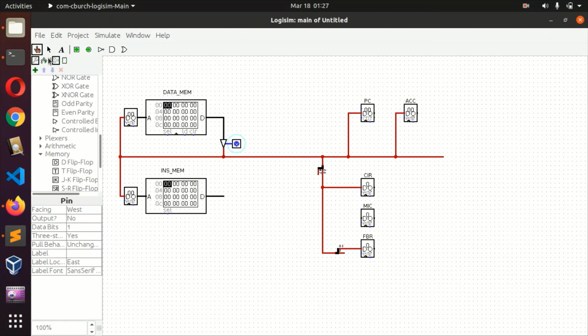It's almost as if you have disconnected what is here from what is here. Basically, the buffer, when it's off, has a very high impedance. So if current is here, it can't go through, because the impedance seen from here to this side is very, very high. So when the buffer is off, nothing can go through, which means this now has a high output impedance. That's exactly what we wanted.